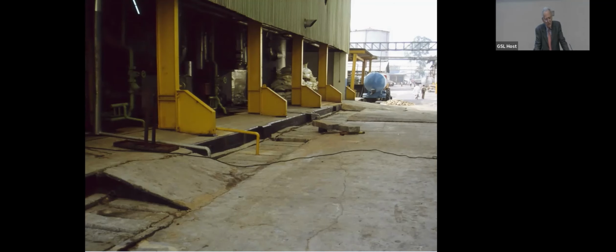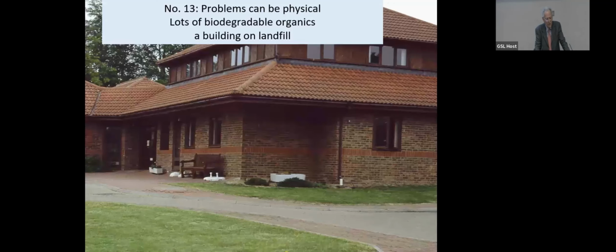But if the chemistry isn't enough to worry you, let's just have a look at this very happy little building built on a landfill, piled, so there'll be no problem with settlement. But if we look there, there's just that little white cuff on the bottom of the downpipe. The ground has settled that much. One wouldn't have known, except that whoever needed to put that cuff on the bottom of the pipe, because the ground had gone down that much, hadn't got a bit of brown plastic to put on and got a bit of white instead. Perhaps no harm done there.